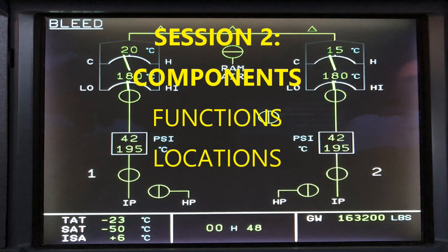This is a butterfly type valve as well. It acts as both a shut off and a pressure regulating valve. The minimum pressure necessary to open up the valve is 8 psig, and it's going to limit the static pressure. You've got static and dynamic pressure; here we're talking about static pressure.